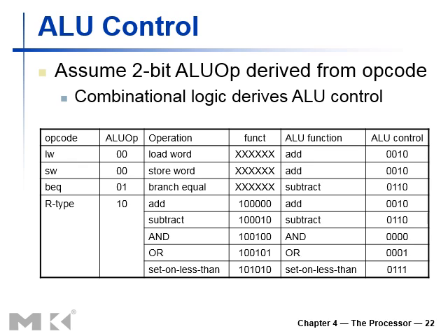Similarly, we get a 2-bit ALU operation control signal from the control unit, derived from the opcode, and this table represents for which sort of operation we require which function values, and for those particular function values, what would be the status of ALU control in order to perform that specific operation. If you remember the 6-bit function bits that are in the machine code of the R format instruction, they are handled here in that scenario.